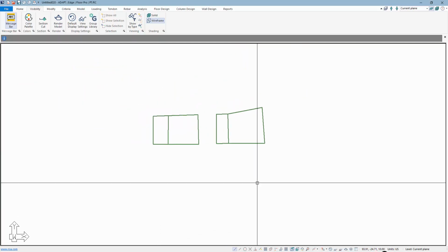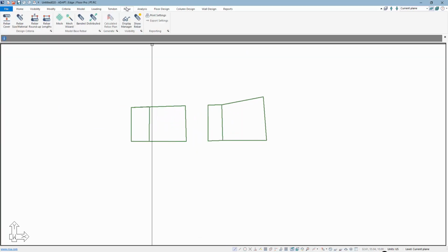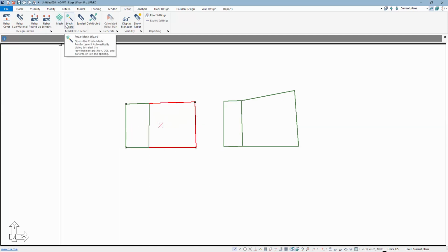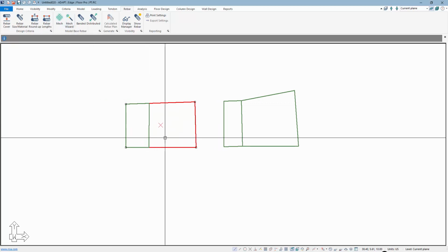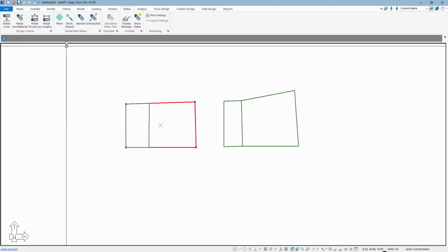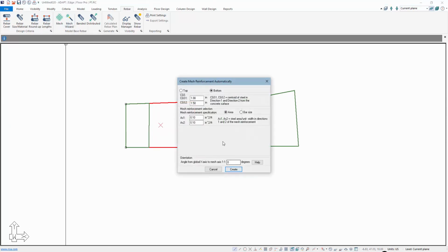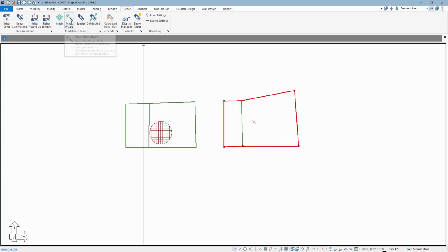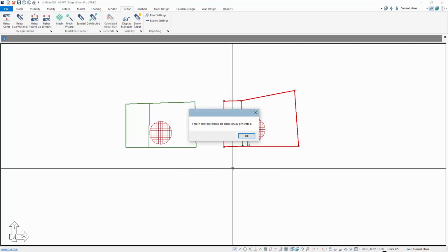And we want to add now bottom reinforcement. The bottom reinforcement, this is considered base reinforcement. It can be in the form of a mesh, banded reinforcement, distributed reinforcement. So if I go ahead and I select this slab, let's say I select that slab, and this is intended for the thinner slab. It's intended for the 8-inch slab. So I go ahead and I create a bottom mesh. Okay, and we'll do one here. We'll create a bottom mesh.